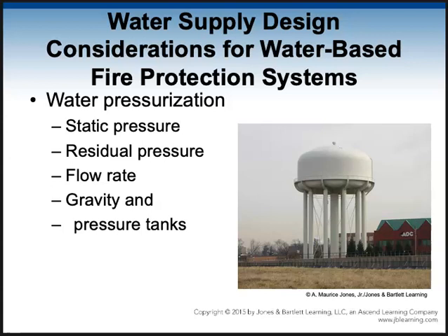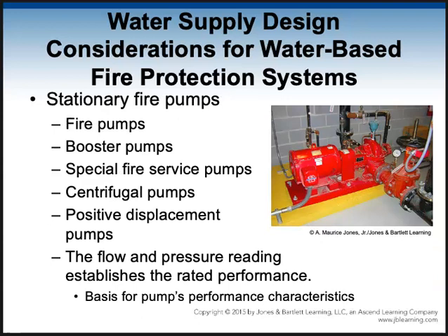Well, what if the system is inadequate? What if we have a high-rise building and the water that's coming in is 100 PSI, which is great if we're at ground level or even a couple of floors up. But when we get up to the 80th floor, it's not going to make it. So that's when oftentimes they'll require pumps to be added to the building just for their fire system.